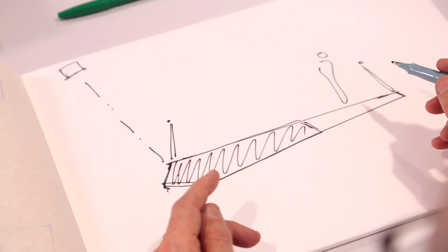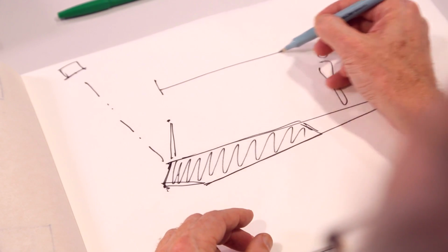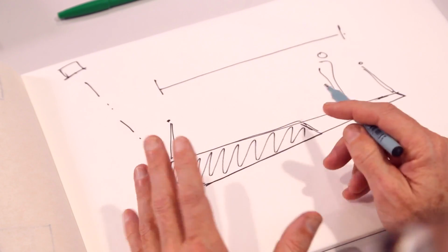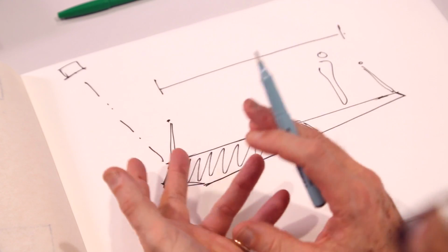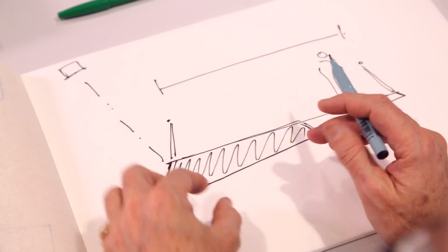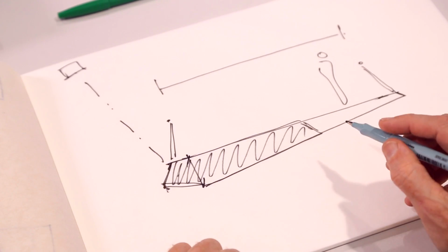Incidentally, another rule of thumb, if you're spanning like a cantilever, as this one is, then I tend to think in terms of something like 1/6 or 1/7 of the span as the sort of depth that you're going to need at the root of your cantilever. But that is another way of solving the problem. We're dealing with the functional cross-section, we're looking at the plan elevation, and like I said before, you're looking at all three at the same time: cross-section, long section, and plan.